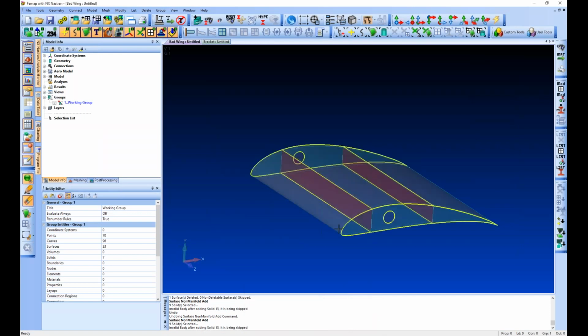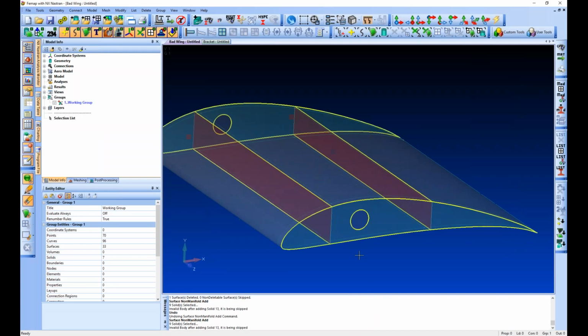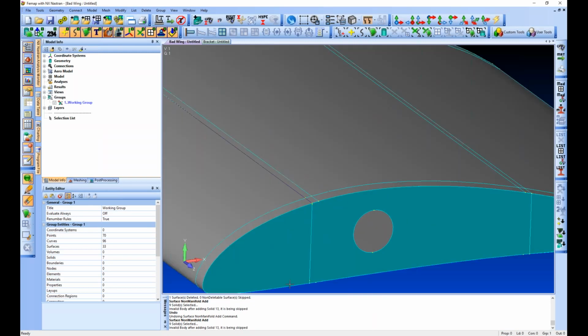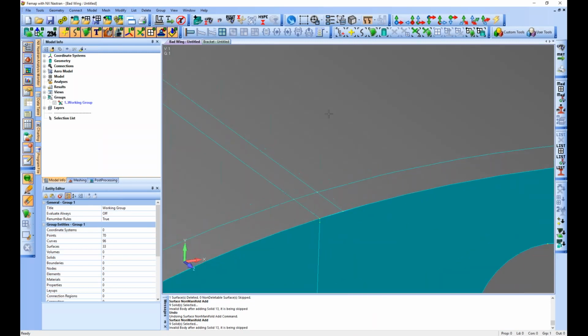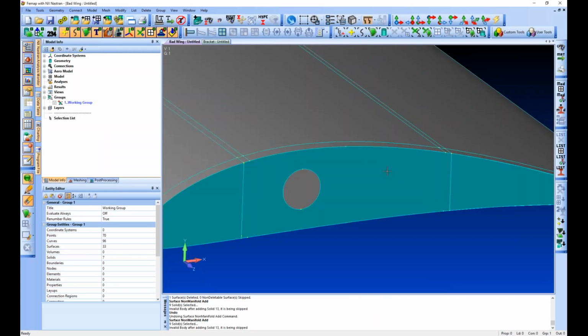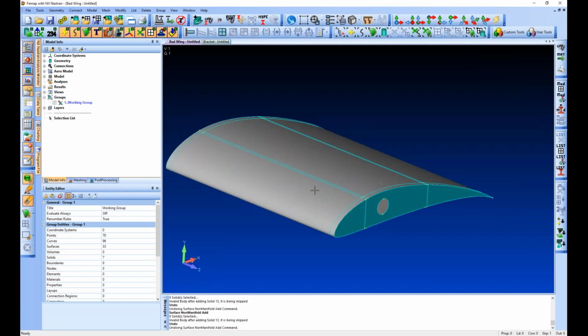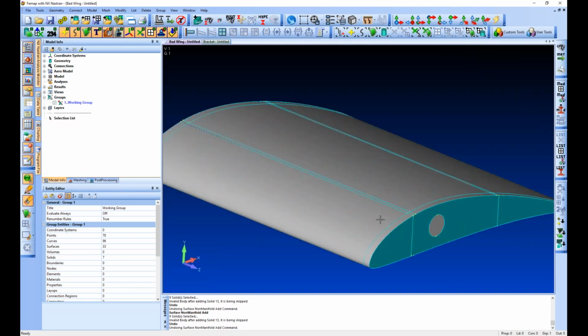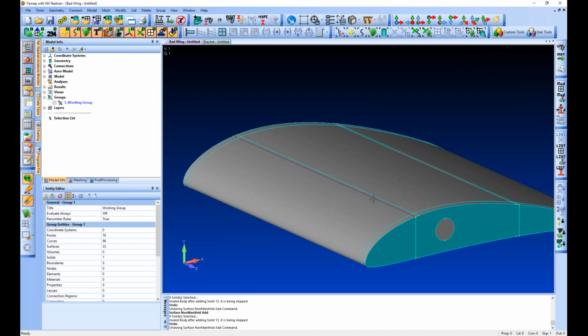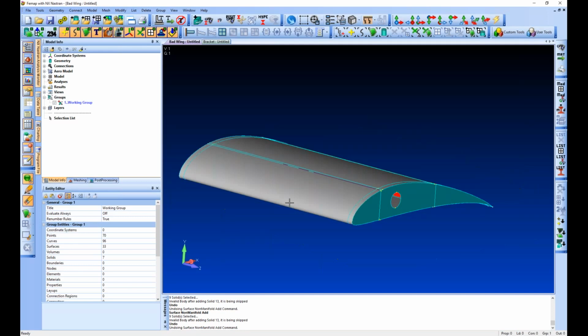Also doesn't work. So in this case, obviously these are all perfect surfaces connected, so the tolerance wouldn't fix something like that, but it's always a good thing to try. What's happening here is actually that we have a bisecting surface contacting a solid that's already been non-manifold added.